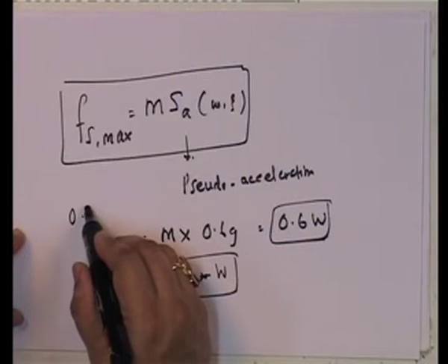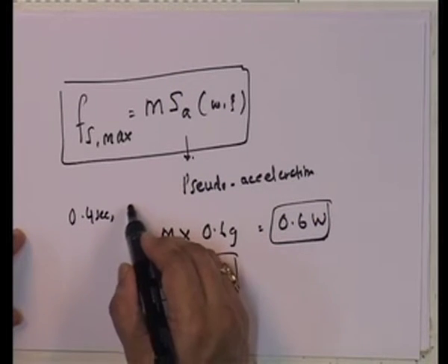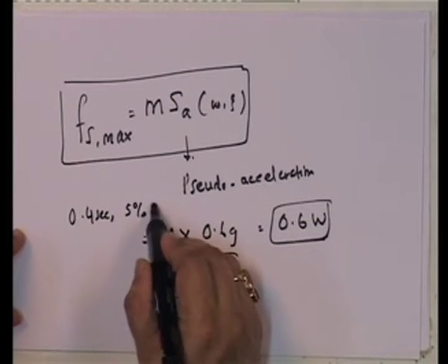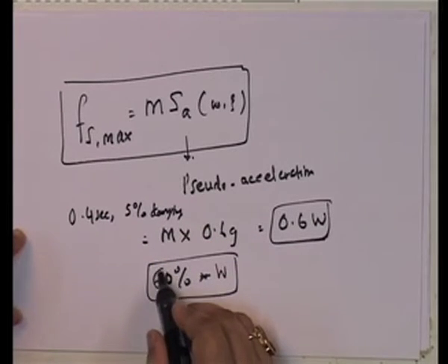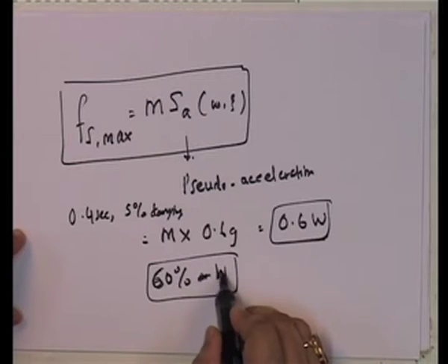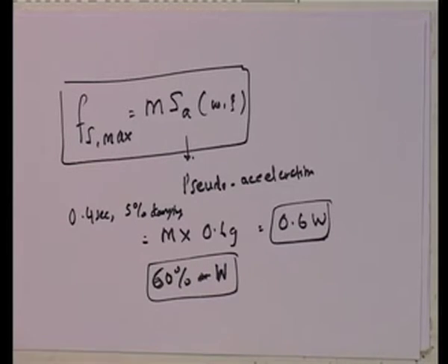I have just done it for a 0.4 second structure with 5% damping, and the force is 60% of the weight of the structure. Very interesting. The response spectrum and its use gets highlighted through this procedure.